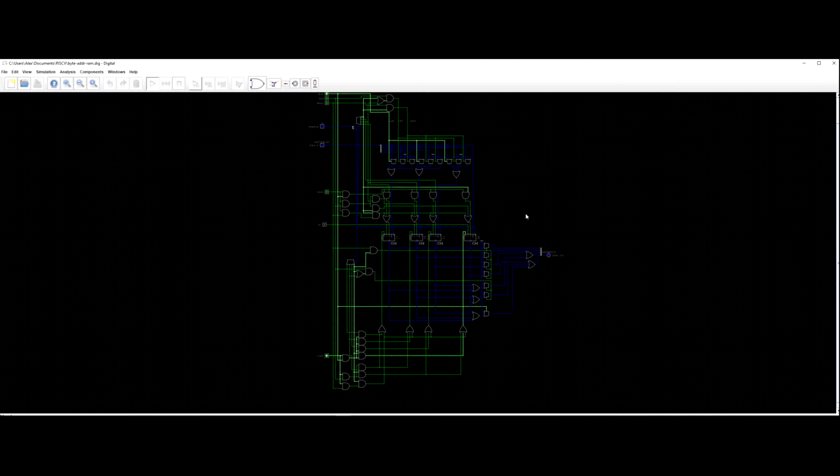Well, guys, we just built byte addressable RAM. So we have a shit ton of RAM. 2 to the 26 bytes. 2 to the 24 words. So 2 to the 24, let me do that math. 2 to the 24 is, we have 16 million words.